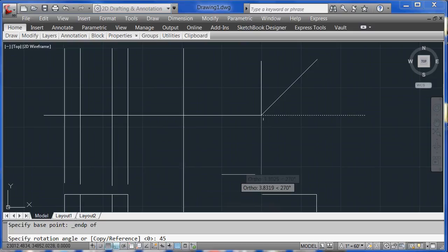But now I have to put in my holes, okay? And this hole that goes in here is, let's see, that's 1, 2, looks like it's 1.5 units in diameter. And this one, it's hard to read, but it looks like it's just 1 unit, the hole that would go here, okay? And so what I want to do now is I'm going to go ahead and offset some of these lines halfway through this width so that I can locate where this hole is.